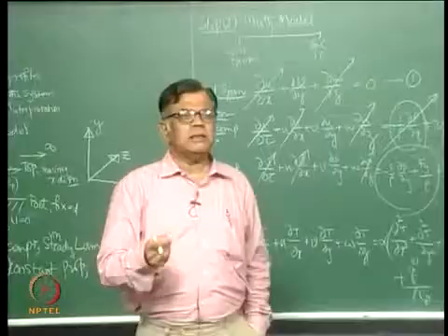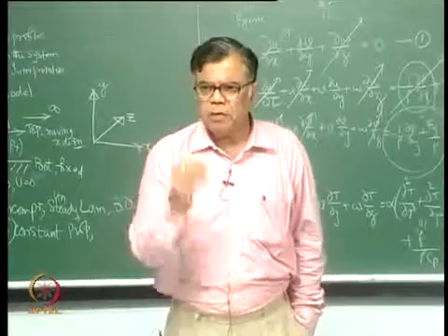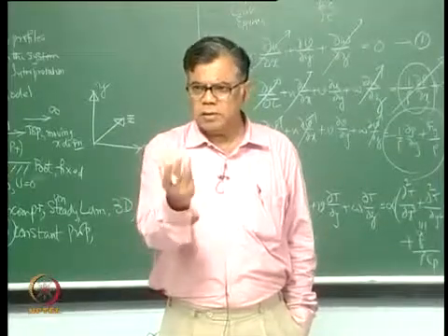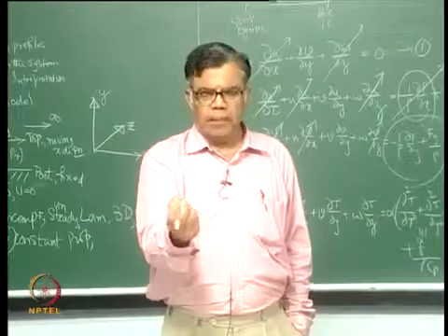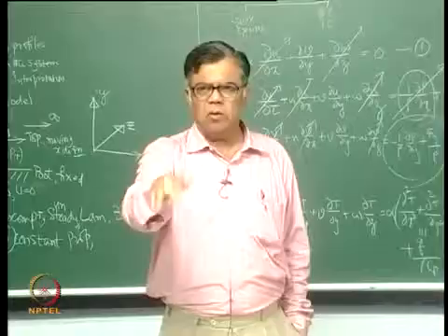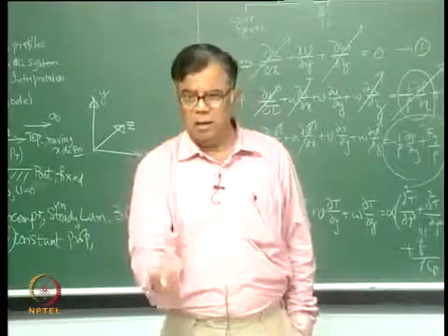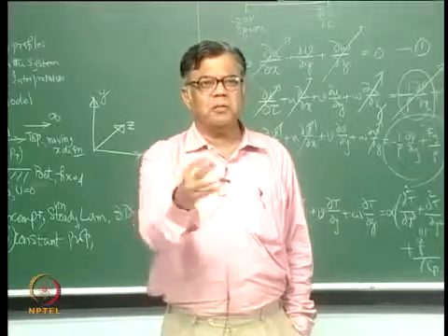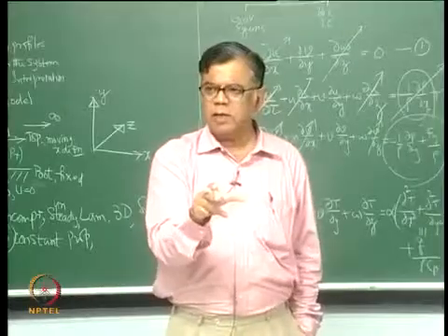Fy is the y component of the body force. The only body force is g. What is the force there? Give me in terms of the variables. So rho g, and in what direction is rho g? No, y direction, upward or downward. So it should be rho g prefixed with a minus.